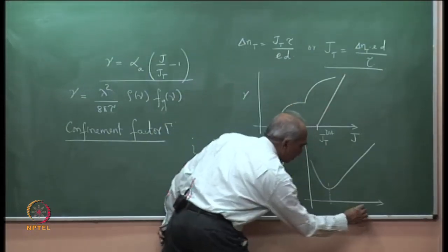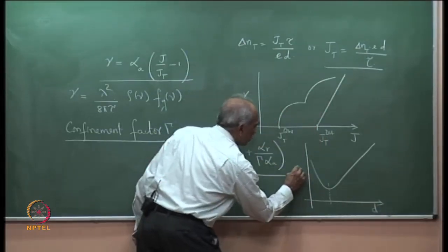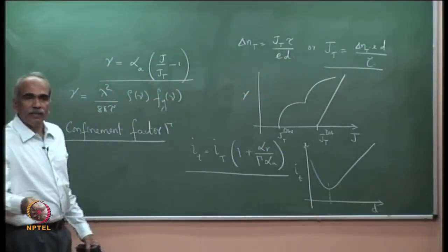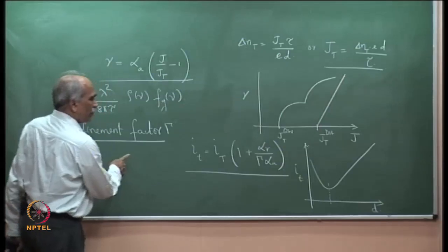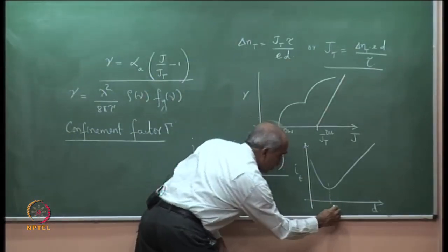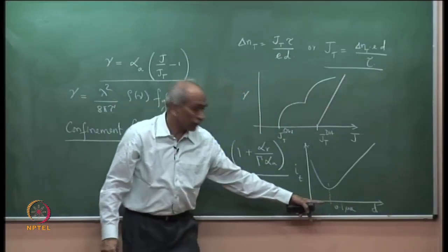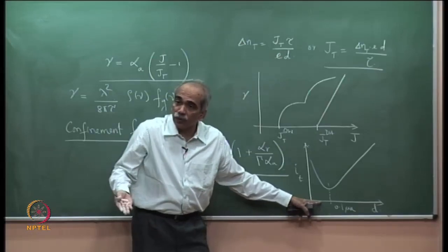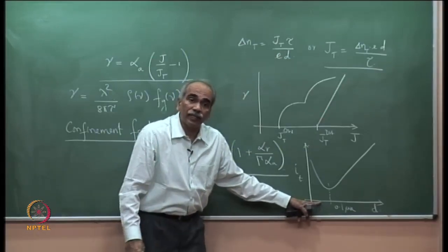So, what I have plotted is thickness D here and threshold current, IT or JT, any one of them. In the case of a quantum well structure, the D is on this side, because this is about 0.2 or 0.1 micrometer, where the minima comes out around here, whereas in a quantum well structure it is 0.01 micrometer, that is 100 angstrom, 10 nanometer.